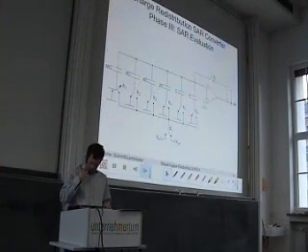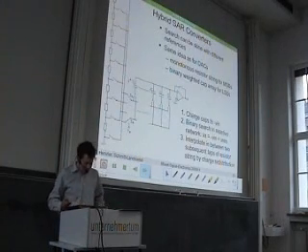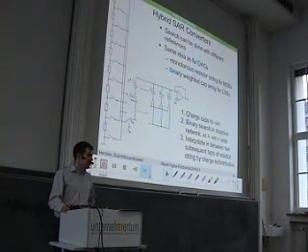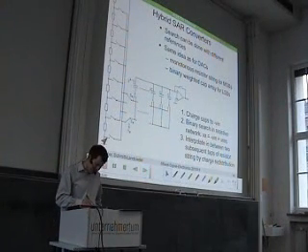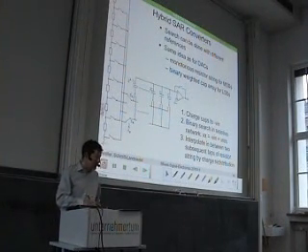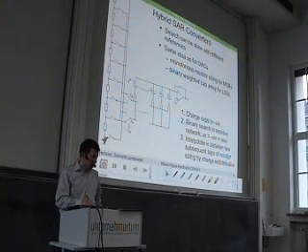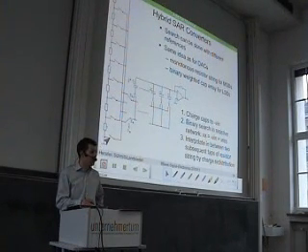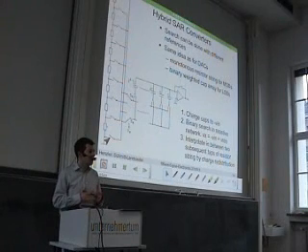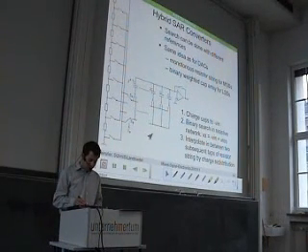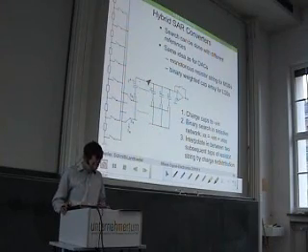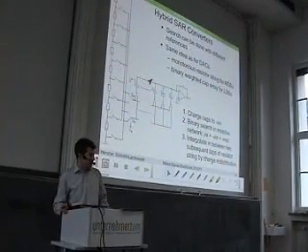Or what you can do, as shown on this slide, is to choose a combined approach, where you do a coarse search in a resistor string. And here you have the advantage, as for the DAC, that the resistor string is inherently monotonic. And then for the LSBs, you might use a binary search technique in such a charge redistribution array.